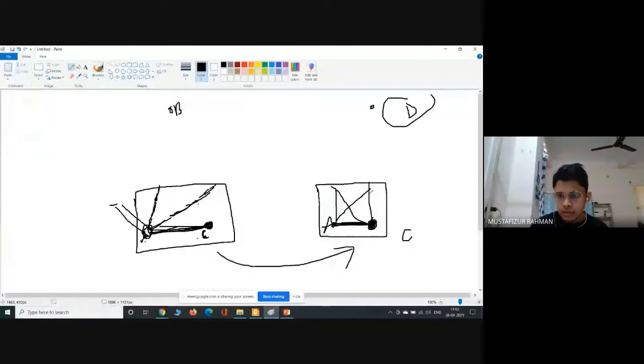So this is called intersection. These intersecting lines will give us the correct position of the B point and D point on the map. Okay, then also if we join these 2 points, we will get this B point and D point. Then already we have drawn this map with the scale. With the help of that scale, we can also find out, okay, the BD line will be this much. We will measure this map distance, apply this scale, and we will be finding out the real distance between the point B and D. So this is called method of intersection.